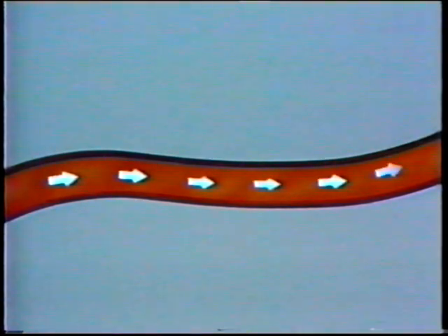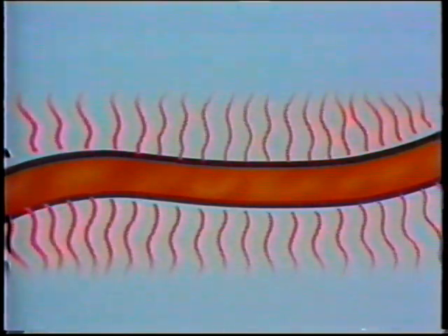The maximum ampacity of a conductor is the maximum amount of current a bare conductor can carry without overheating. You're aware of the fact that when current flows through a conductor, that current meets some resistance, even in the best conducting materials. Energy is required to overcome this resistance. That energy is given off as heat. When the maximum ampacity of the conductor is exceeded, the bare conductor may overheat or melt.